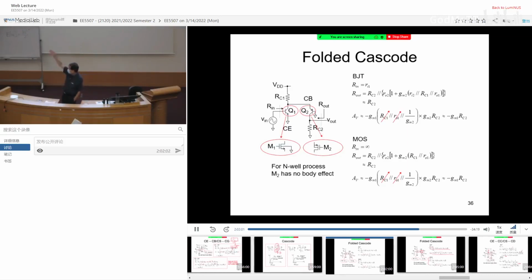If you have so high a ceiling, cascode, no issue, right? I stand on the chair, fine. I still have so much room to climb, right? Stack the chair, still got enough. Stack another chair, still got enough. Am I right? But if you keep stacking, eventually you are going to reach the ceiling. Agree? That is the problem with cascode. You can keep cascoding, but the voltage of operation just gets higher and higher. Eventually it is going to reach the limit.